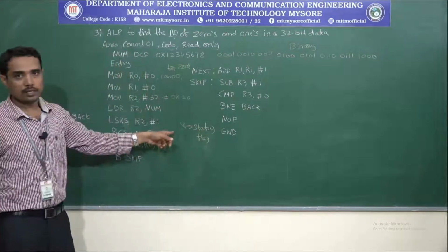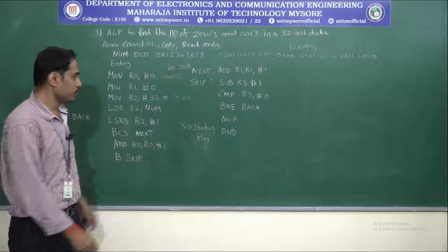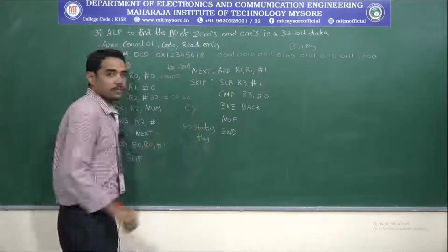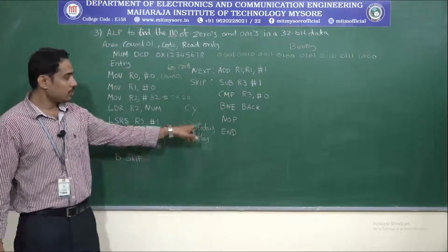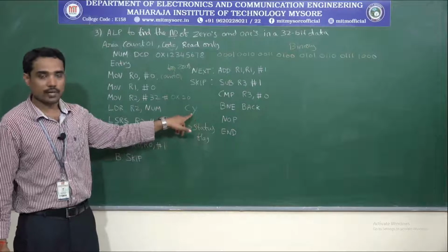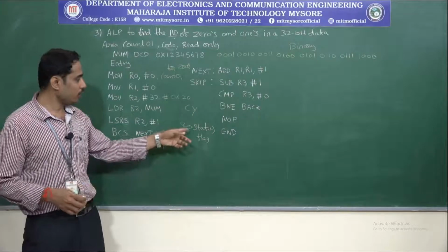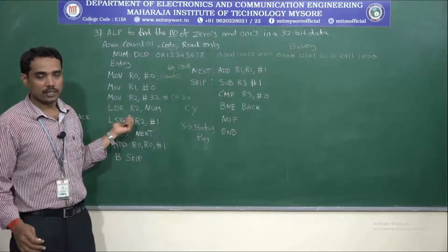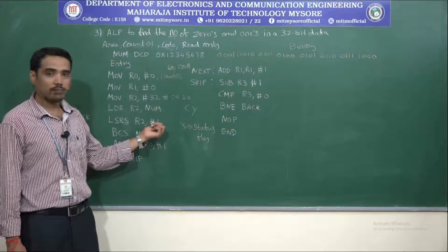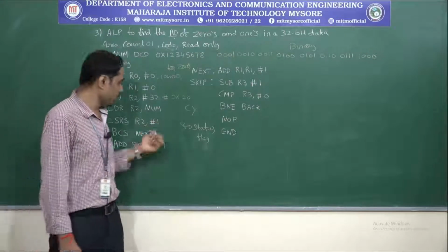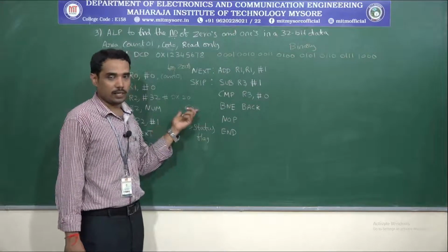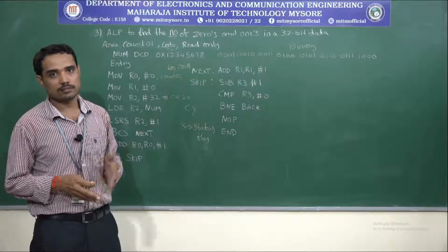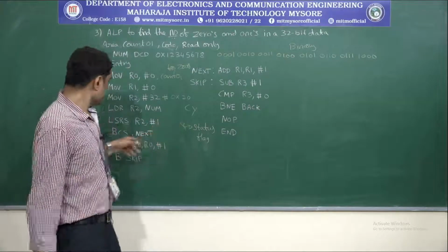Here we are considering the status flag of carry. What is the status of carry after shifting the data towards right logically by 1 bit position? Then we have to check the status of carry, if the carry is set or reset.